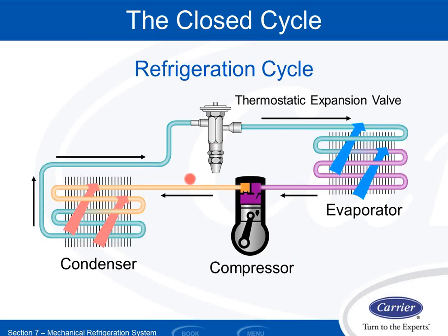If temperature goes up, now when that refrigerant goes outside to the condenser coil, it's hotter in the condenser coil than it is outside in your yard. So he has to give the heat up, right? That's how I'm able to move heat from the inside to outside, even though it's hotter outside. I change the pressure of the refrigerant, which increases his temperature, which now makes him hotter than the outdoors, so he can reject his heat at the condenser. And then that quote-unquote cool refrigerant can come back into my TXV. My TXV is my pressure regulator on the opposite side of the compressor.